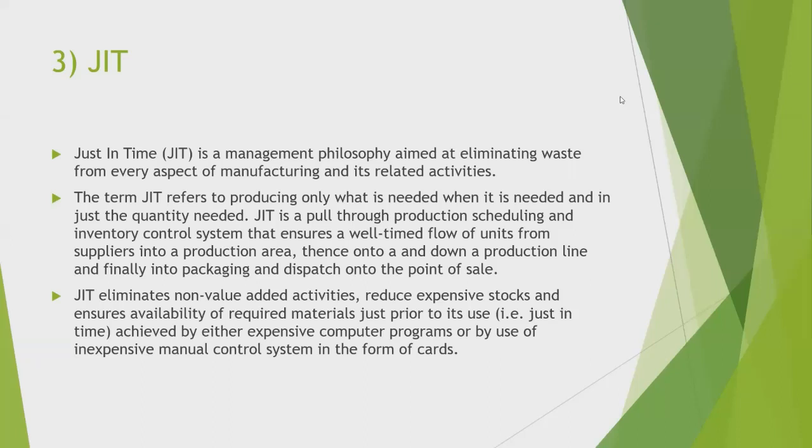JIT is a through-put production scheduling and inventory control system that ensures a well-timed flow of units from suppliers into a production area, onto and down a production line, and finally into packaging, dispatch, onto the point of sale. JIT eliminates non-value added activities, reduces expensive stocks, and ensures availability of required materials just prior to its use, achieved by either expensive computer programs or by use of inexpensive manual control systems in the form of cards.